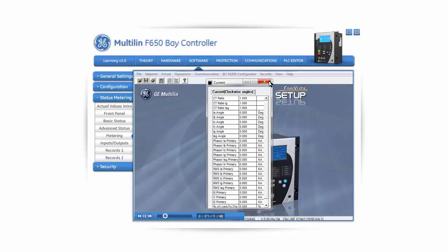or 60 Hz. The user can also monitor the RMS values of the phase, ground, and sensitive ground currents. Here, RMS means that the currents shown are unfiltered, so they will display the value of the current that includes all frequencies present in the signal. And finally, the RMS values of the sequence components and the proportion of load capacity used are also displayed.